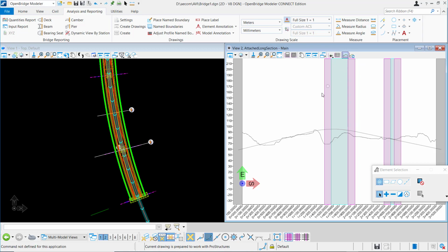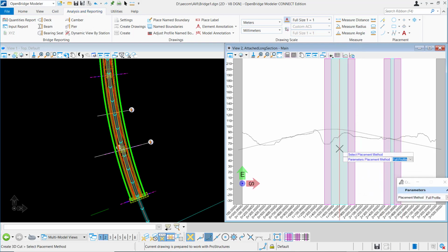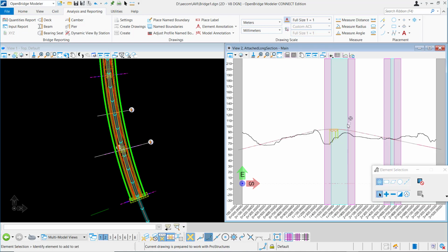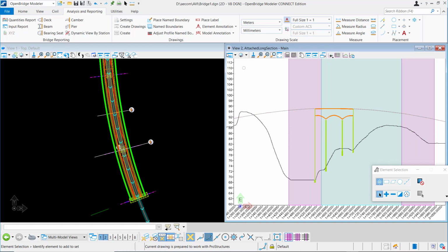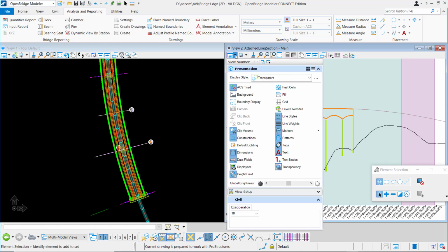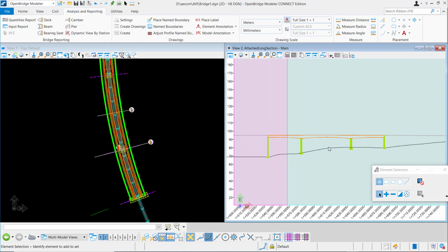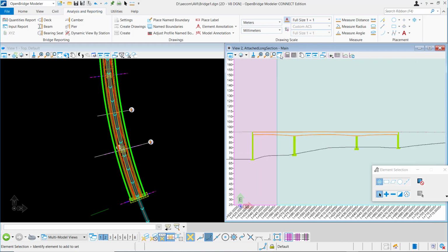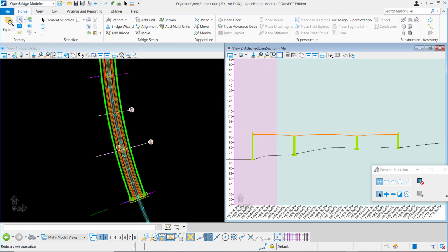In this view, we see how we create profiles. The profile view will help us to create the profile drawing. So in this profile view, we have to ask it to automatically compute the intersection with the bridge. And here we see first the profile view, but only intersecting elements. That's why we don't get all the different details.